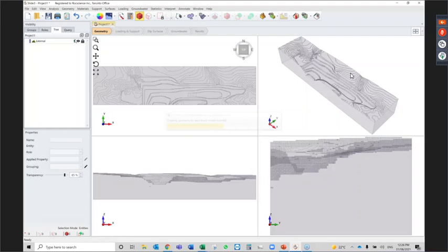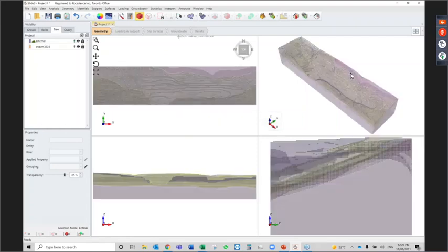Moving on to search methods, these are the different methods available in Slide3. You can search by grid, auto-refine, cuckoo, and particle swarm, and then also apply search filters by elevation, volume, depth, and weight. I'm now going to show you results of a case study. Different search settings have been applied. This is a simple open pit mine with 4 materials, all isotropic. At default settings, the factor of safety reporting at GLE is 1.85.